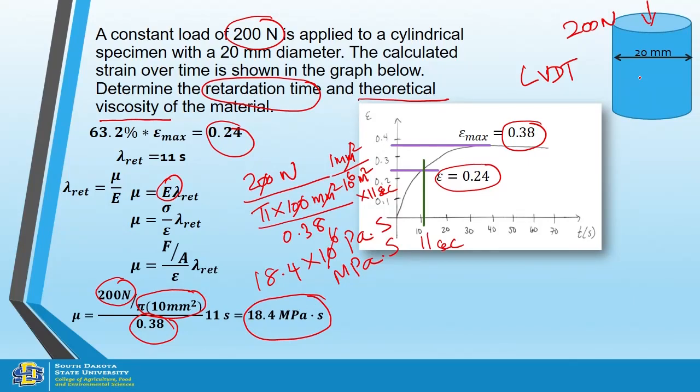When we come back at 4 o'clock, I will explain how to do dynamic rheology, where you can do an oscillation test instead of this compression test. You can do an oscillatory stress test, where you can get the elastic modulus and viscous modulus of this material.